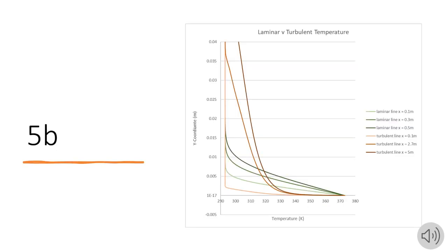We can see that the temperature graph behaves similarly to the velocity graph. The laminar case is an almost linear trend of cooling until it reaches the free stream where a constant temperature is achieved, whereas the turbulent case has a larger boundary layer as fluids of different temperatures are constantly mixed together and the transition to free stream is not as steady. This larger turbulent boundary layer causes colder parts of the fluid to move closer to the surface of the plate. This causes a greater temperature difference, which results in greater heat transfer.